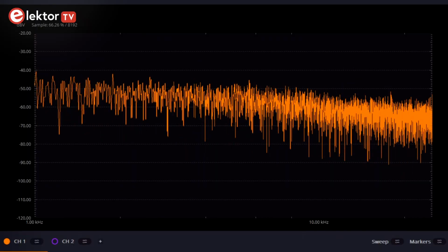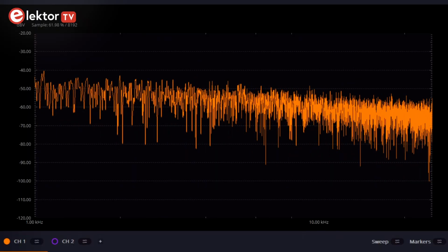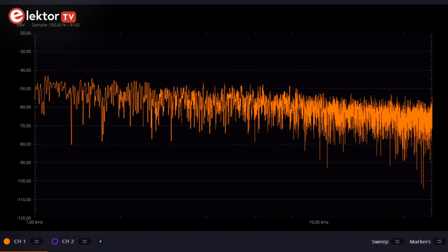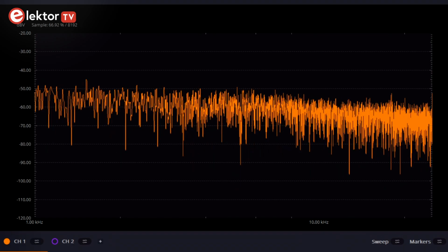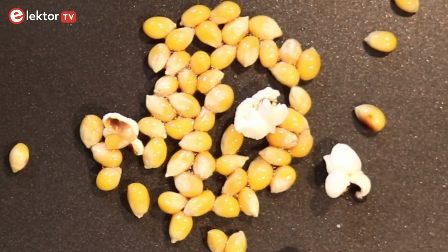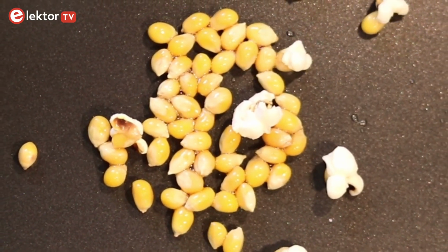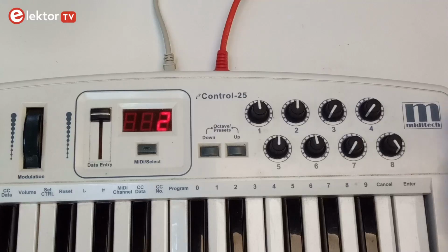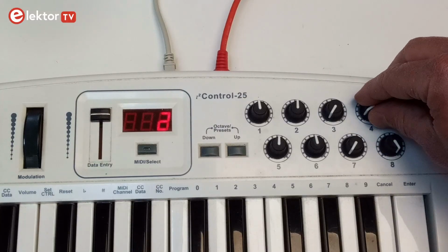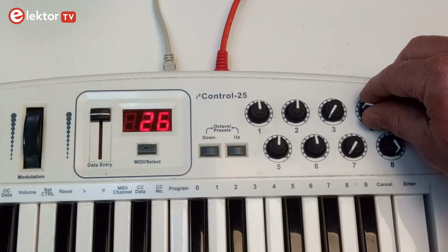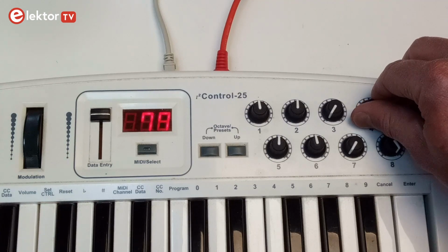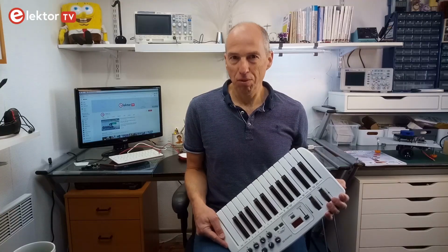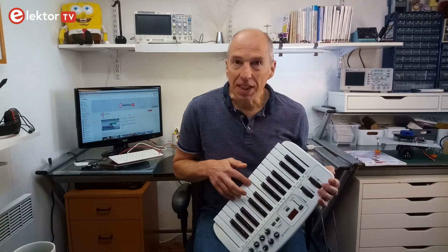Pink noise, or 1/f noise, has a spectrum with a slope of -10 dB per decade. The spectrum of red noise, or Brownian noise, has a slope of -20 dB per decade. Popcorn or crisp noise is obtained by clipping the output of the noise generator. There are 2 flavors. The PRBSynth1 also lets you control the length of the random number sequence to obtain a gradual change from noise sounds into pitched sounding repeating patterns. This is called pattern mode. The pitch of these patterns is mapped to musical notes and can be played with a MIDI keyboard.